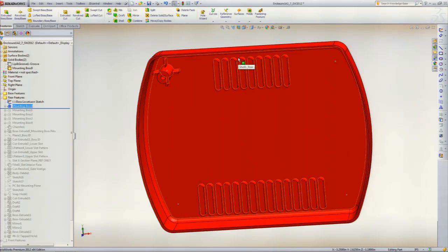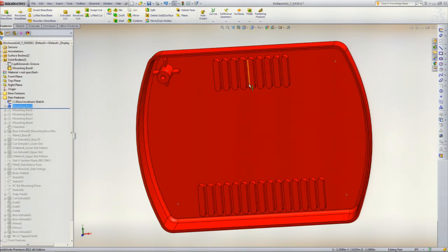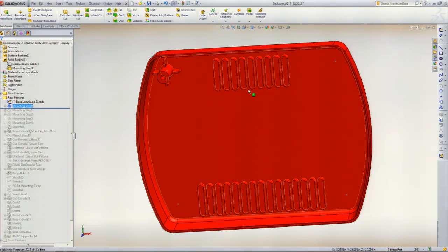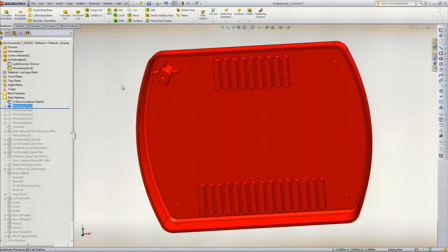Yes, you can. You can't select it in the boss manager tree. So you can also select the different heights, the thicknesses of your fin geometry. You do have to go in afterwards and add chamfers if you want them to be angled gussets. So that's a separate operation. You just use your chamfer tool.